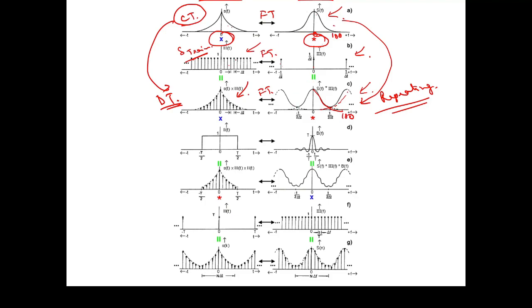Okay, so when we are doing the sampling, we have to band limit the signal before going for the sampling.